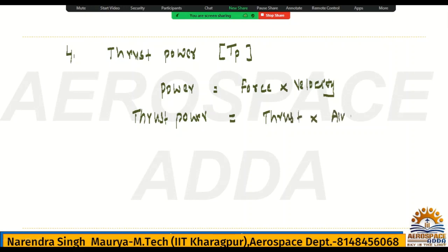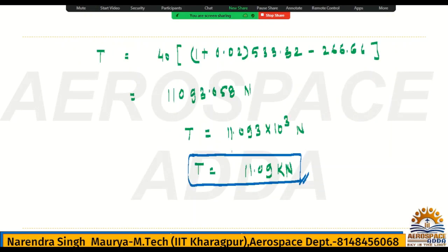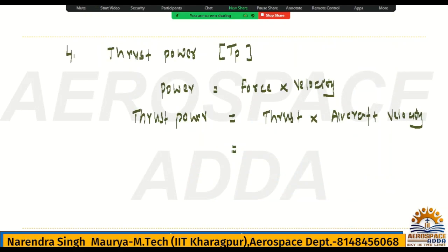Aircraft velocity. What is the thrust we have calculated here? Check, 11.093 into 10 power 3. It is thrust into aircraft velocity you had calculated. It was, I think, 266.66, if I am not wrong, please check it. So what is the thrust power?